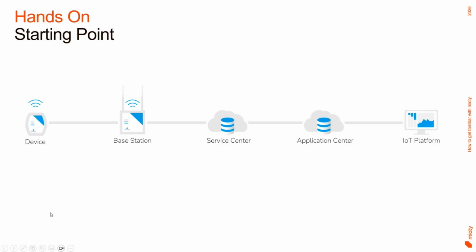The nice thing about mioty is that everything is standardized. So we have the mioty protocol level from the device to the base station, and then we have the BSSCI to the service and application center. And from there, you can use a standard protocol like MQTT to really easily fetch your data.